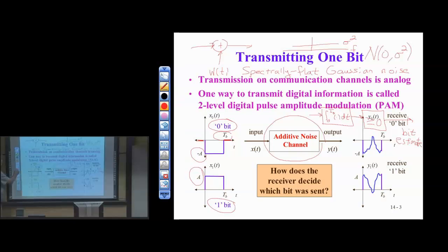The process you just described, is that done with analog hardware? Yeah, right now all I've done here is show you the analog continuous-time story. But ultimately, we can do this lots of ways. I could put an analog to digital converter on the receiver and then apply an FIR filter over the symbol duration. It's a finite length filter. So really this integration is only over the symbol time, and then I restart the integration over the next symbol time. So this integration is over a finite period. It's just an averaging filter.